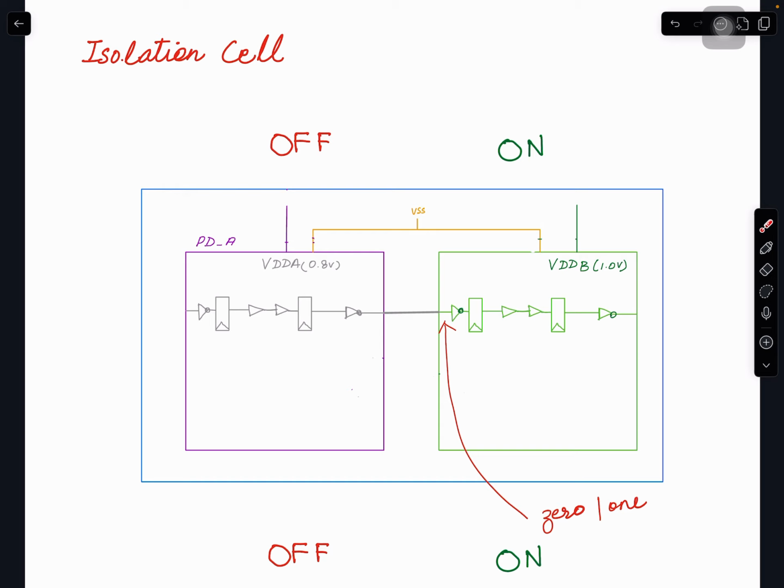Whoever defines the UPF, by the way, it is first used in simulation, and then the same UPF comes to the physical design, first in synthesis. So before the isolation cells can be put in the place and route tool, they go in the synthesis tool as well. I have used it in the synthesis tool. Your synthesis starts with an RTL that doesn't have isolation cells in it, but the UPF describes them, right? Based on the UPF description, the synthesis tool adds isolation cells on those interfaces. It knows where those crossings are happening, and then it puts isolation cells.